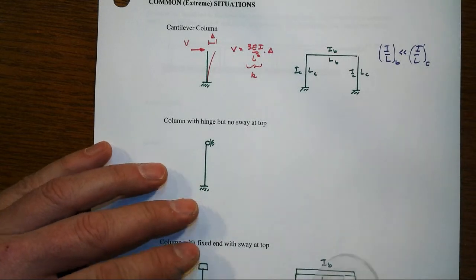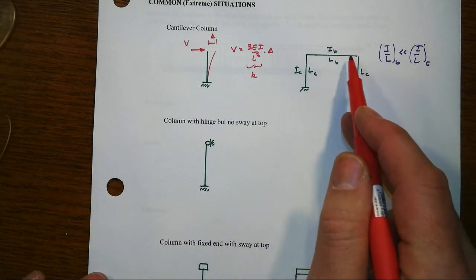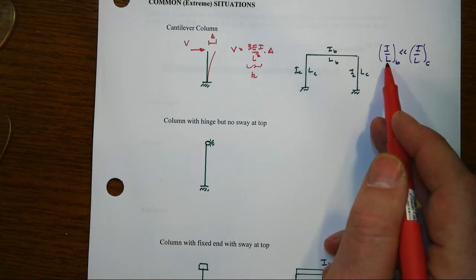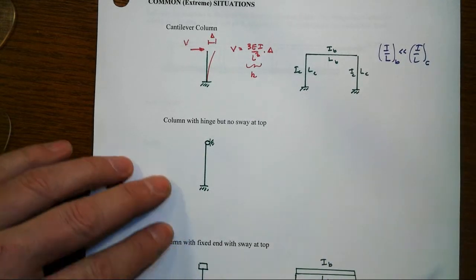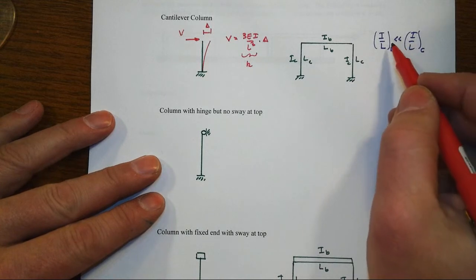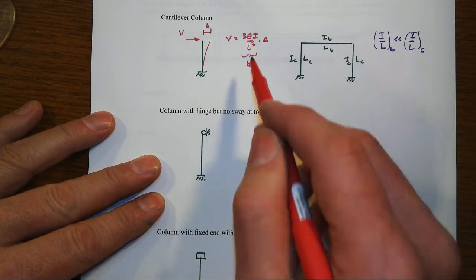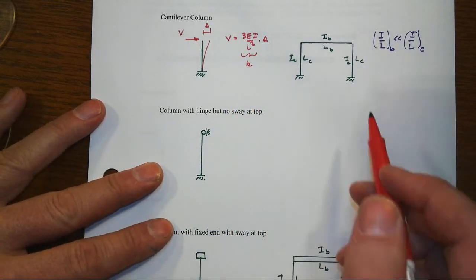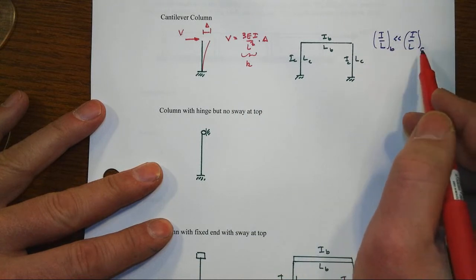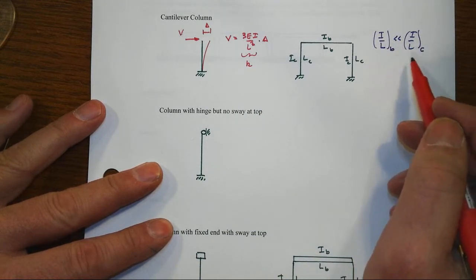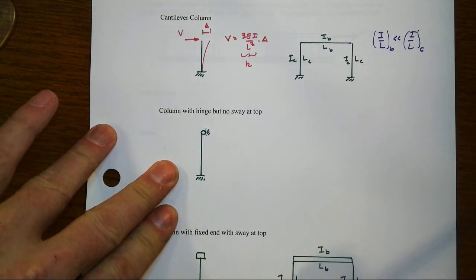And that's very useful in earthquake engineering, that we might be looking at a system if we believe that the beam is relatively flexible compared to the column. That usually happens because the length of the beam is so much longer than, say, the column. And it may be that we need to look at some, not I over L, but I over L squared, L cubed, the kind of thing that you begin to see here is one of the ways that we might begin to look at this comparison. In other words, it's not just a one-dimensional comparison. We might have to look at a range of things before we believe that we have this kind of situation.